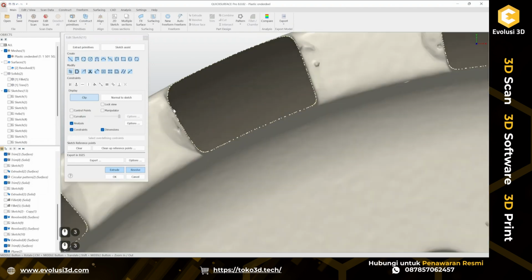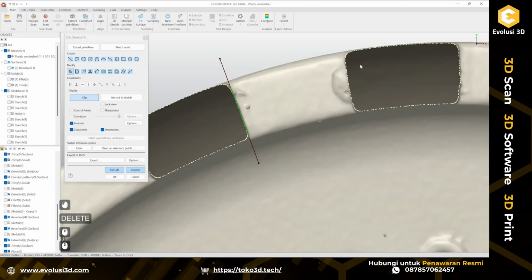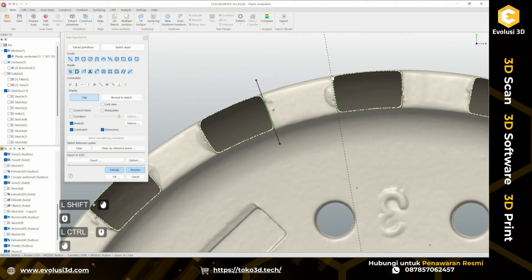And let's see what we can actually do here. So let's select these slice points and these ones to fit entities. Let's extend them longer. Actually, probably I don't need this one, but I want to use this one just to create a sort of cutting tool.